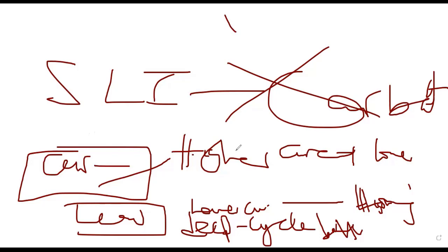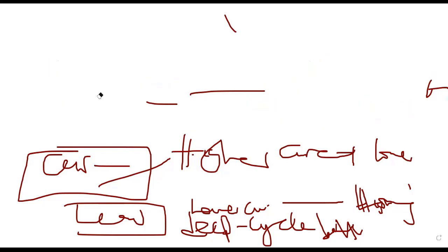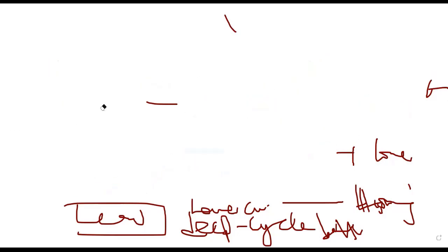And by the time you are driving the car, you are charging back. But a deep cycle lead acid battery is designed to give you continuous current as you demand, for deep discharge. That means for a longer period of time. So this is what you need to understand when you are talking about deep cycle lead acid batteries. So car batteries are not allowed for solar energy systems.